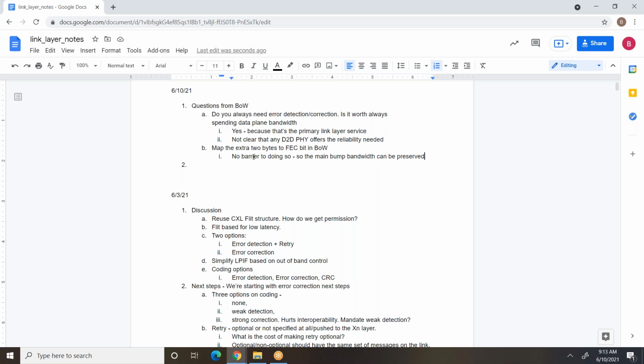I don't have like 16 bits and then these 2 extra bits for miscellaneous. It's not like the BoW. A lane has either 8, 16, 32, or 64 bits, and then I can have n number of lanes. The width of the lane is a multiple of the flit width.